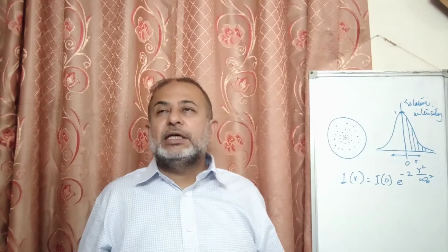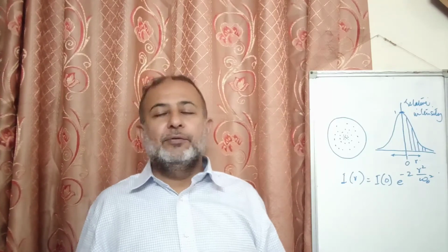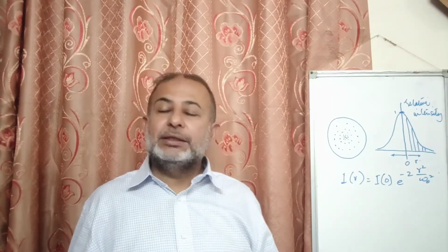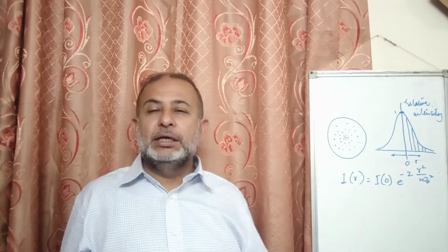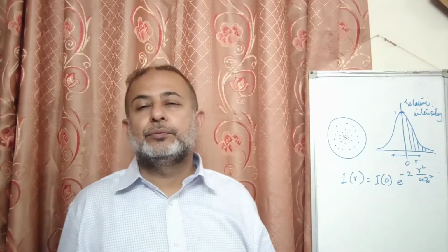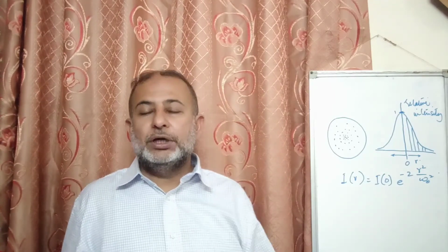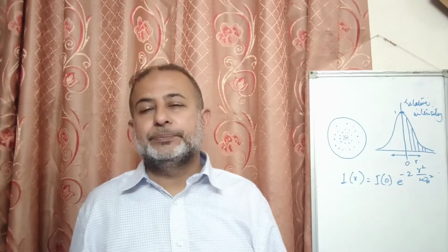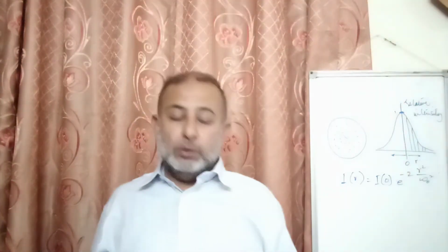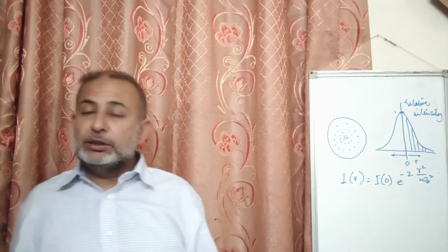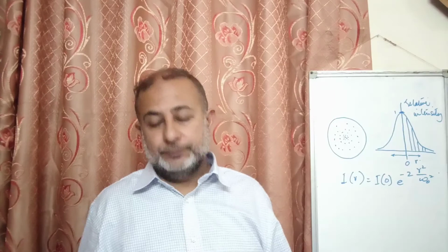But what happens is that if we use light that has a wavelength lesser than 1310, then definitely it would lead us to additional modes, even if we are using a fiber with a core diameter of 8.3 micrometers. For single mode fiber, the operating wavelength is always longer than lambda c.